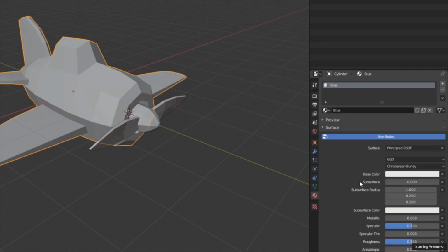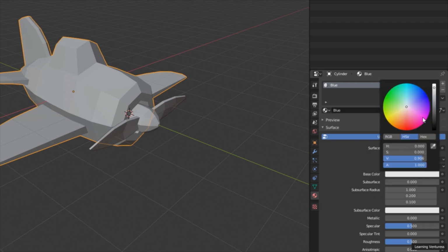In this crash course, we are just going to talk about the base color of the material, that is the color itself. So, if we click on this field here, besides the name, where we can see this color wheel, where we can choose the hue of the color and the saturation, and this column here in the right, where we can choose the darkness of the color.